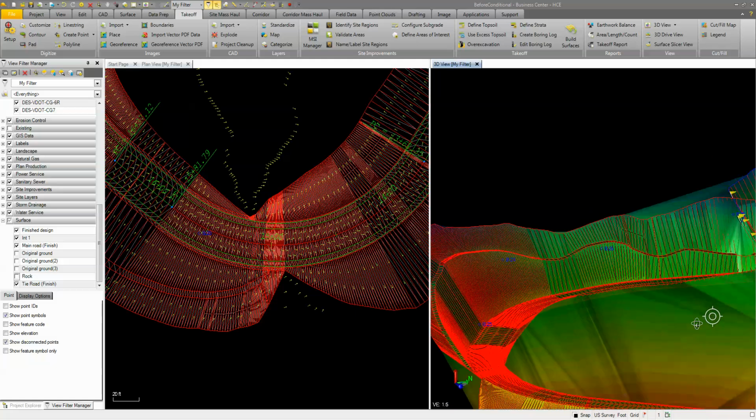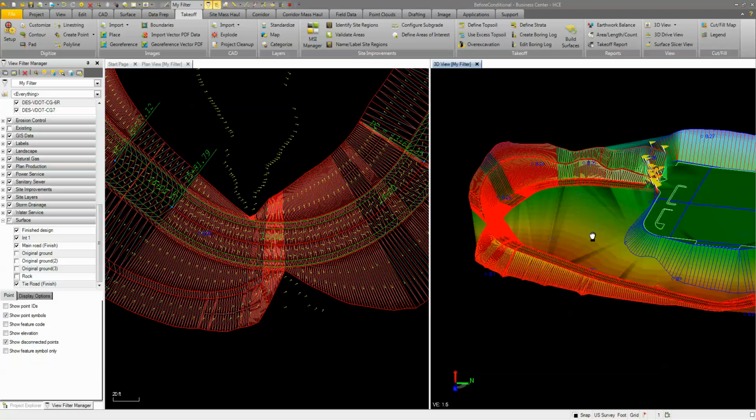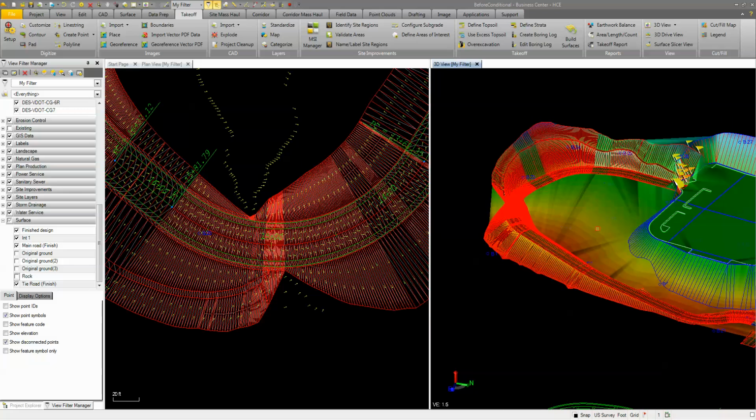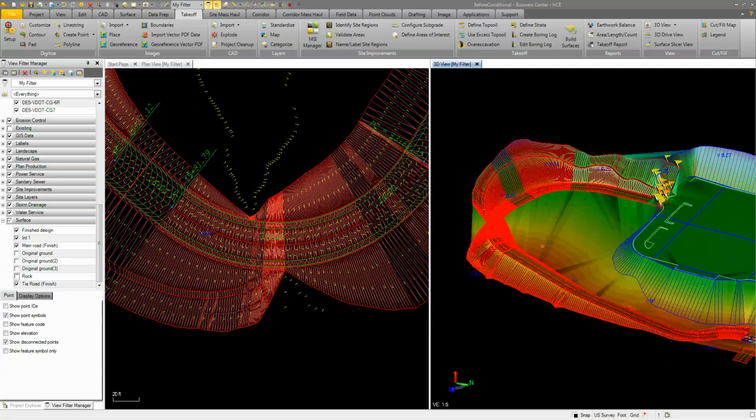through the project. Okay. Now we do have some cleanup we need to do, like over here, but that's one way that you can add in that conditional template to determine whether you're in a rock cut or above or below the rock, and have a different slope or a different condition happen depending on what that if or else statement determines.